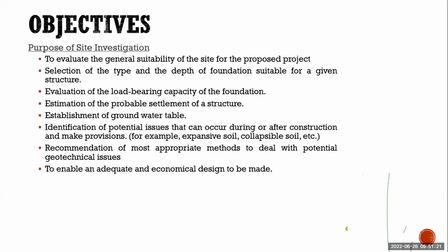Then evaluation of bearing capacity. Especially for any foundation, we need to know the bearing capacity and the settlement characteristics of the soil. So if we are going to construct, let us say our foundation pressure is going to be 200 kPa, and the soil bearing capacity is 150 kPa, of course you cannot build that structure on that particular soil.